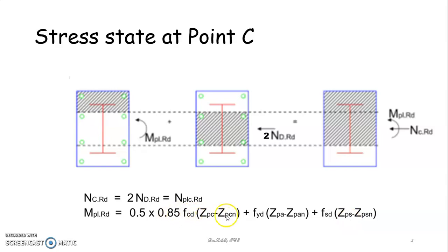If you substitute the respective values in this expression, you will get your plastic moment of resistance. From this you have to know the location of this h_n distance from the CG of the cross section. From the upper portion there is an h_n, and below the central axis you have an h_n. So the total height of this region is 2h_n. Here we are going to see how to locate the distance of your neutral axis from the CG of the cross section.